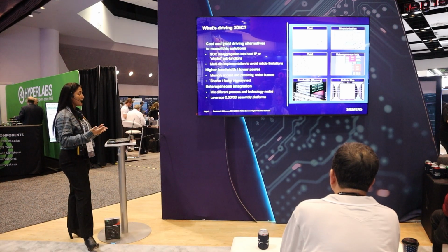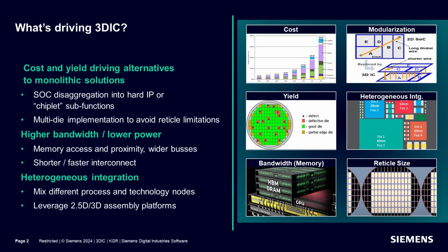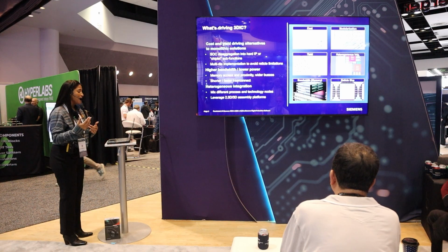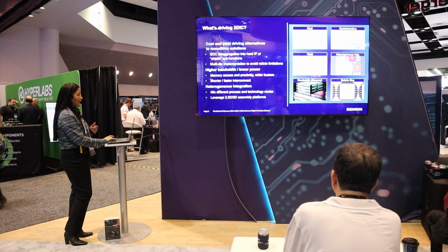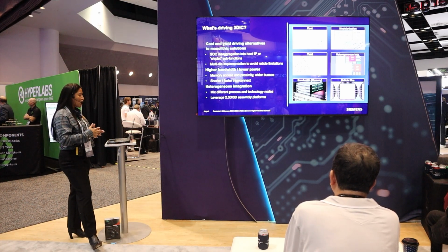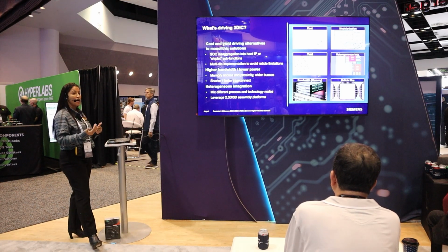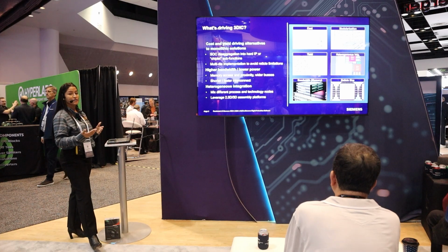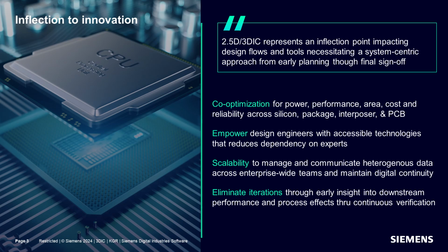And these approaches are driving the adoption of interposers and RDL build-up technologies such as fan-out wafer-level packaging to improve connectivity. And this enables greater design flexibility, allowing engineers to optimize trade-offs between cost, performance, and power efficiency. Some of the new design challenges and really our path forward: while heterogeneous integration provides a path forward, it also necessitates new design methodologies and tools that can analyze systems holistically. And this combination of multi-die architectures, right, from chiplet-based designs, HBM, UCIe, and advanced packaging is paving the way for more efficient, scalable, and advanced solutions.